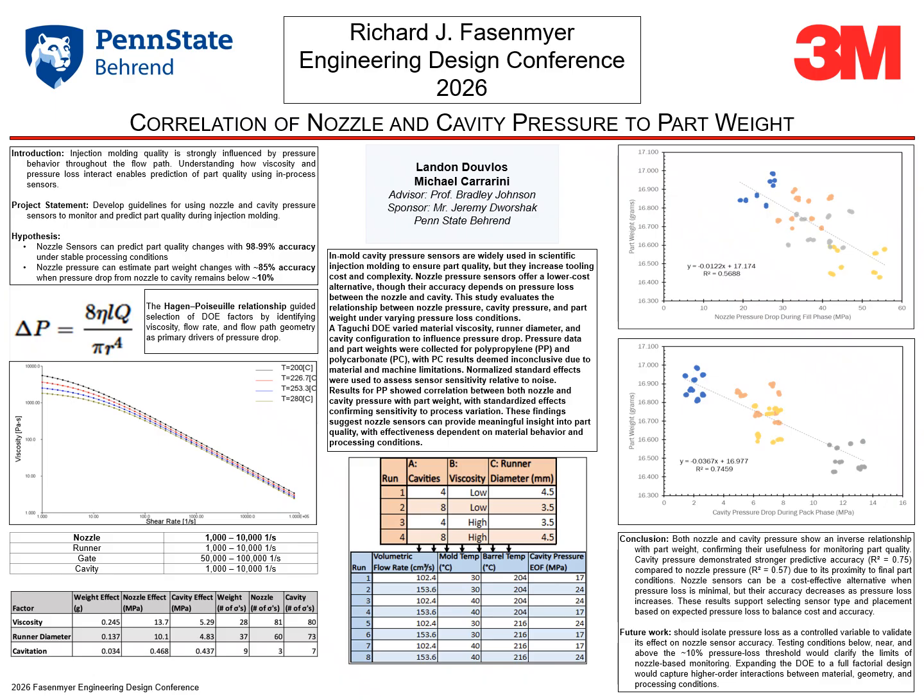Results for polypropylene showed correlation between both nozzle and cavity pressure with part weight, with standardized effects confirming sensitivity to process variation. These findings suggest nozzle sensors can provide meaningful insight into part quality, with effectiveness dependent on material behavior and processing conditions. So, an introduction into the project.